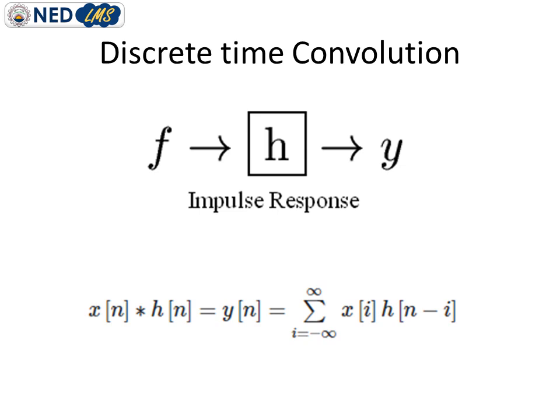This process of decomposition, calculating the output for every impulse and then adding up that output, is basically the convolution. Since we are dealing with discrete time domain, this is the discrete time convolution sum.